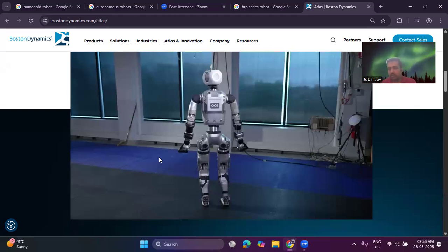The center of mass, or COM, should be within the base of support for stability. These are the key aspects related to a humanoid robot: dynamic balancing, zero moment point, and center of mass. And for the stability criteria, there are two kinds of stability: static stability and dynamic stability. In static stability, the center of mass is within the support polygon, whereas dynamic stability involves acceleration and inertia forces. The zero moment point must stay within the foot boundaries.